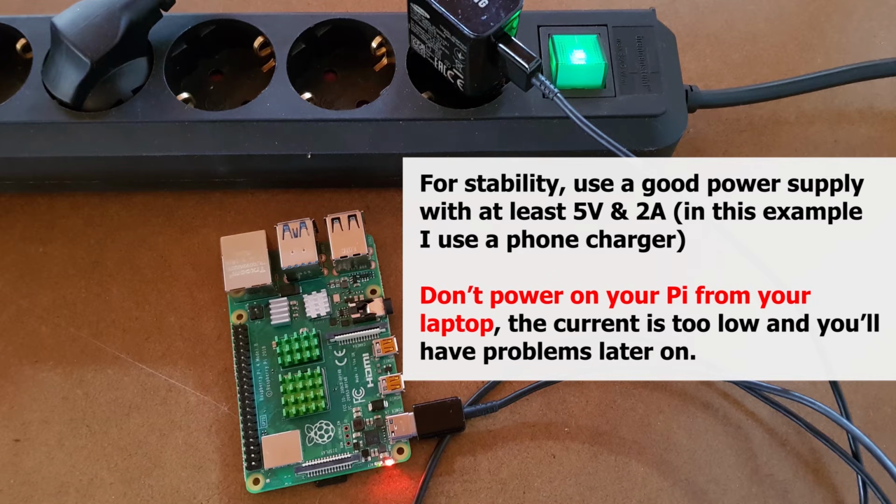When you boot the Raspberry Pi, you will see first a red LED powered on, and then the green LED should blink randomly. If the LED blinks randomly, this is actually a good sign. It means that the Raspberry Pi is booting. And after a few seconds, maybe 1 or 2 minutes, the Raspberry Pi should be connected to your Wi-Fi network, and this is where we're gonna go to the next step and find the Raspberry Pi IP address on the network.